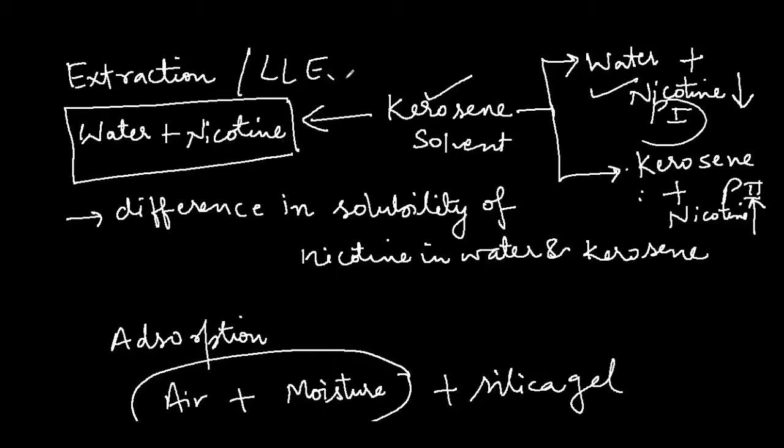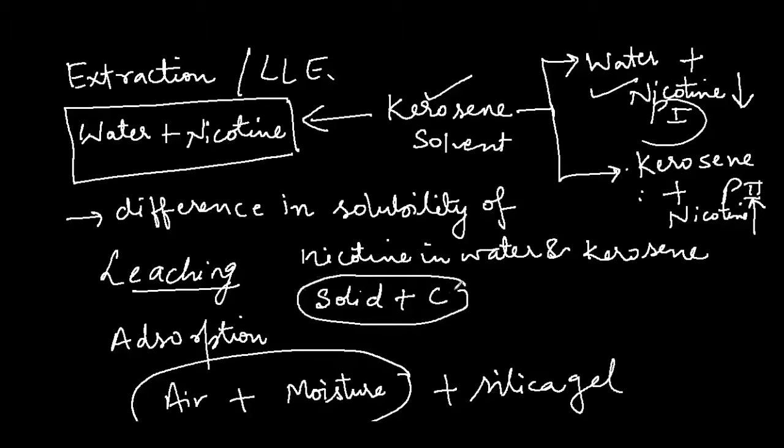A similar principle to liquid extraction is utilized in the unit operation of leaching. In leaching, we have a solid which contains some component, suppose C, that you want to separate. We use a solvent that will extract the C from this material. Take the example of tea in your home, which you make daily.